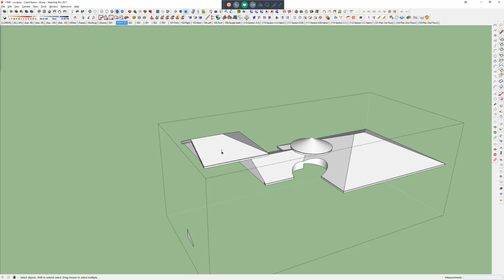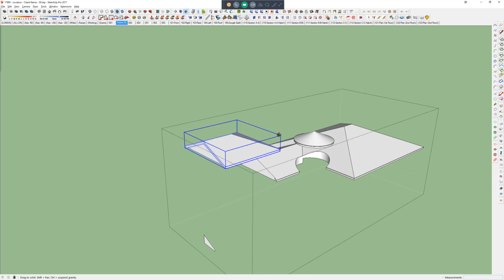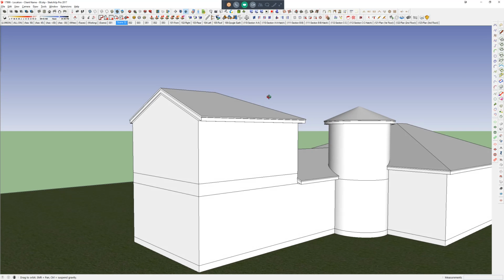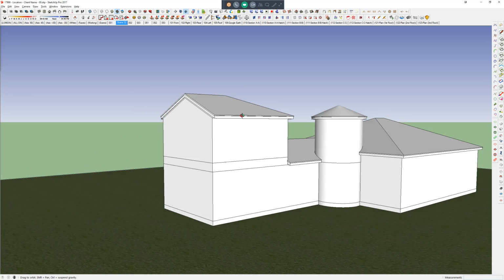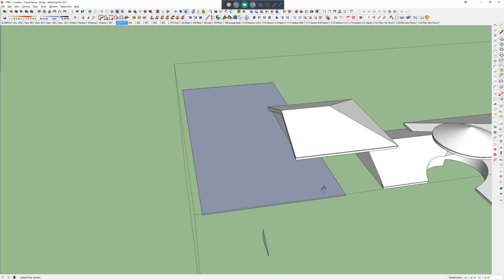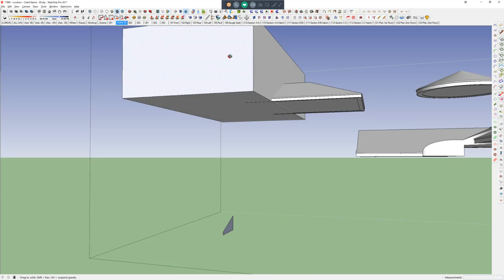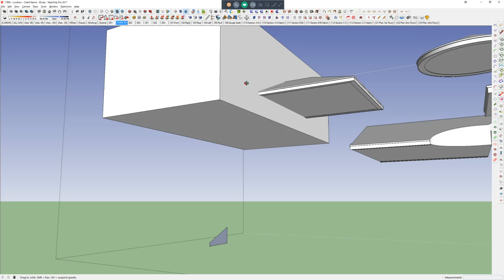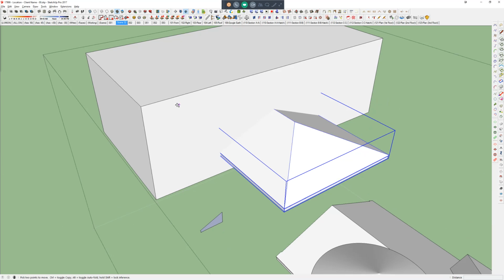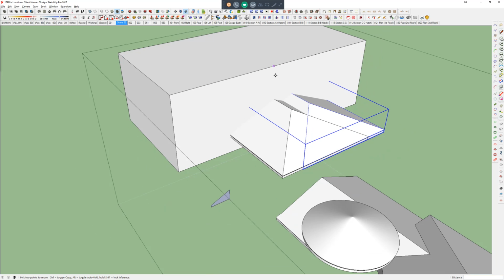And so from here, I'm just going to leave this gable, even though it's not what it's supposed to be for now. But you can see that if they wanted to go back to a hip, I can just make what I call my cutting box, as long as it's bigger than my roof. Maybe I'll just make a copy of my roof sitting over here in space if we want to look at options.